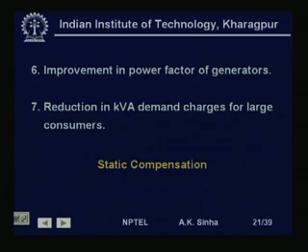Therefore, reactive power compensation helps in relieving extra capacity or relieving overload on the equipment, and that is generators, transmission lines, etc. It also helps, as I said, if we increase the power factor, it helps the generator also, because it will have to generate less amount of reactive power, which means that the excitation system will be working with lesser current. We do not have to over excite the generators.